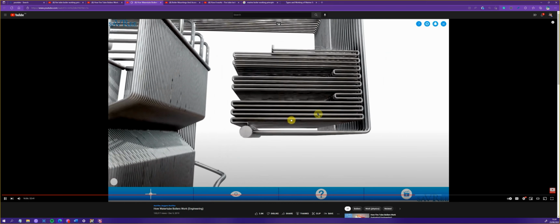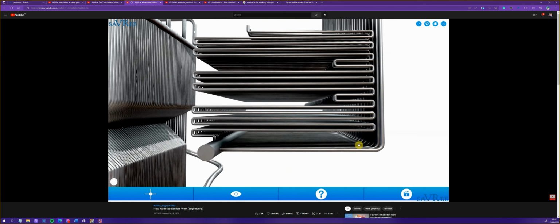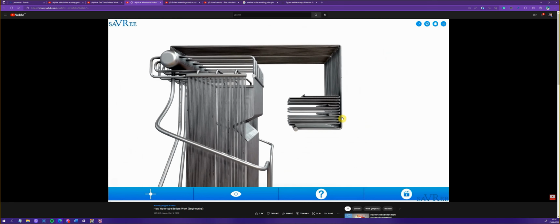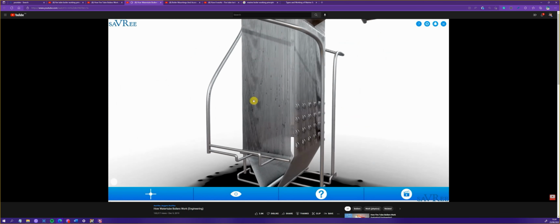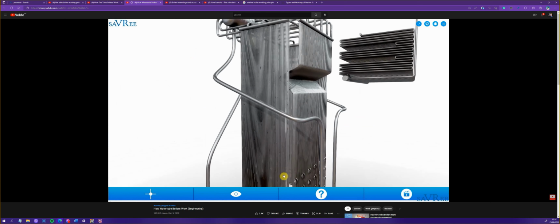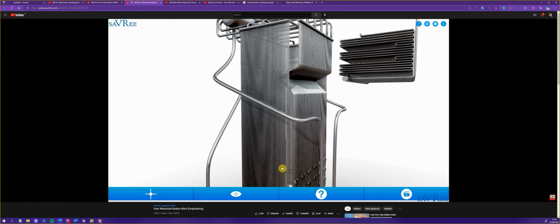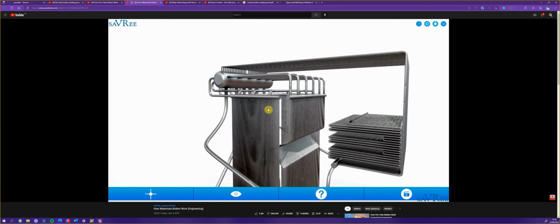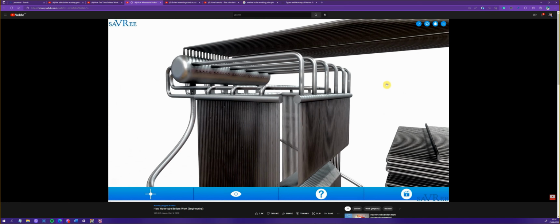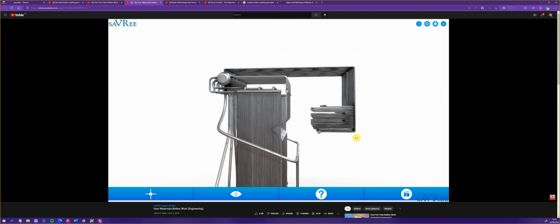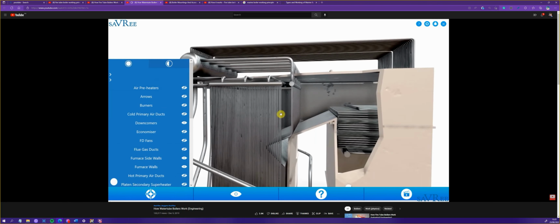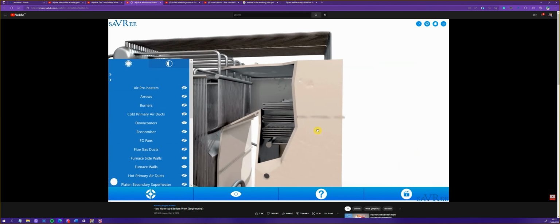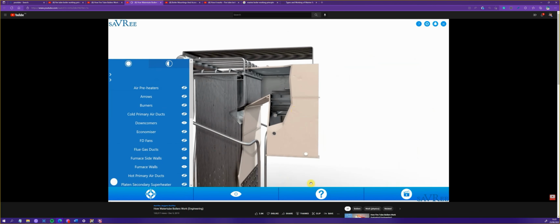Now we're adding more heat in our primary superheater in order to heat up that steam even more. The location of the primary superheater is important. Notice that our actual area of combustion is here. So those hot exhaust gases, which contain significant amounts of heat, are going to blow up here, and they're going to come around the top, and then, in fact, if I add the superstructure, perhaps that would be a better way to show it. They're going to come up around here, and then they're going to flow back down again, and come down here, and then go out.